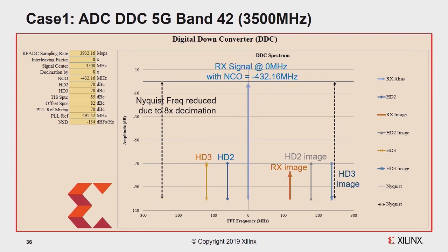And one more thing is our decimation is set to 8 times lower. Our original spectrum is 3.9 gig divided by 2, so our original signal is 1.9 gig, and then we divide by 8 times, so our signal is only 240-something megahertz. So decimation is a kind of advantage.